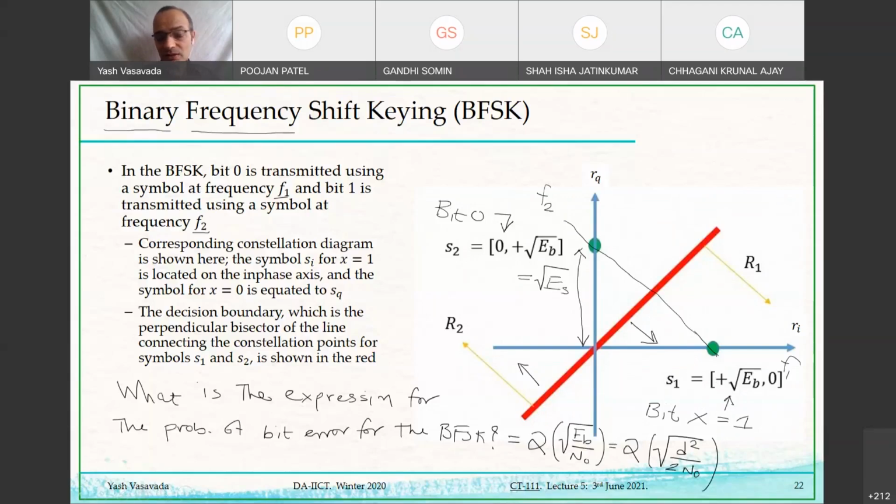It is indeed the case that there are two constellation points on two different dimensions. And the noise, as we said last time, will not have this nice property that one of the two coordinates is 0. And so we have to integrate the noise over, first of all, the noise PDF will become two dimensions. It will not be just P of n anymore. It will become P of Ni and NQ, so it will become a two-dimensional PDF.